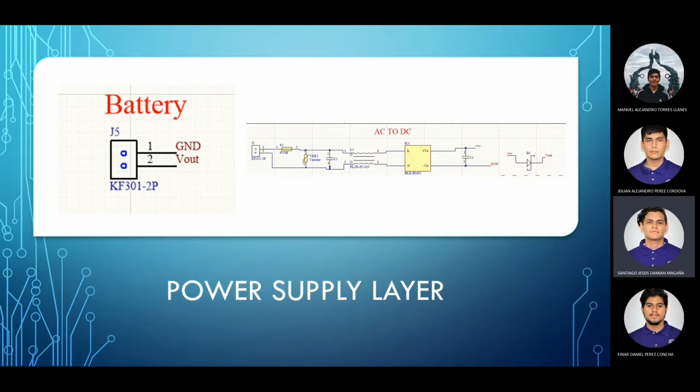With the capacitor, we control the signal being received by removing any noise produced by deviations in the voltage. Then, with the power module, we convert the 220 volts of alternating current to supply 5 volts to the system. At last, the Schottky diode provides a lower voltage drop across the diode at low reverse bias, giving us a safe 5 volts of direct current, making it safe for our microcontroller, the ESP32, and the sensors.